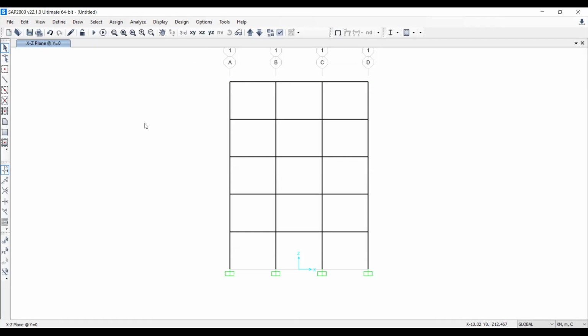What are plastic hinges? The plastic hinge is the location of damage. You know, we are applying the pushover analysis, or the nonlinear static analysis. In order to know the capacity behavior of the structure, we need to know the performance. We need to know the dynamic or static behavior under a seismic event. So I need to know where the damage will happen, on the columns first or in the beams first, on the beams and columns together, how much flexural damage or cracking could happen at the first floor, second floor, in the whole building.